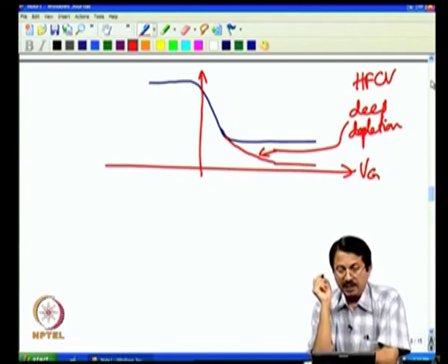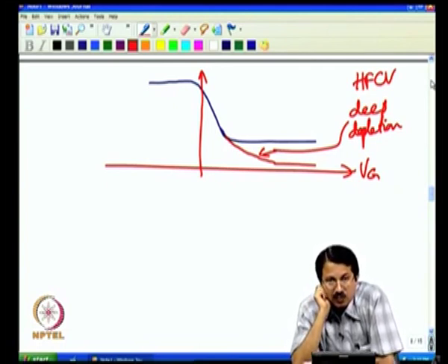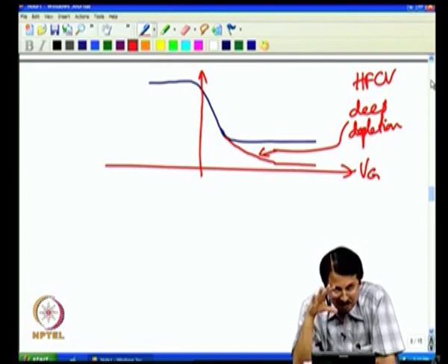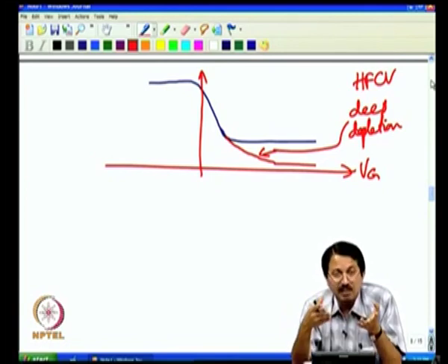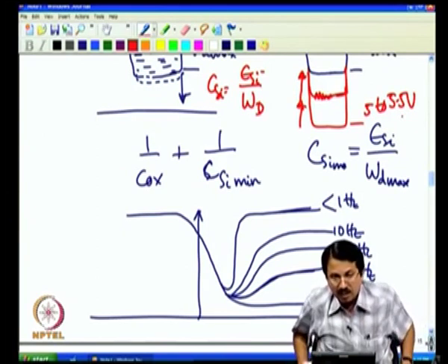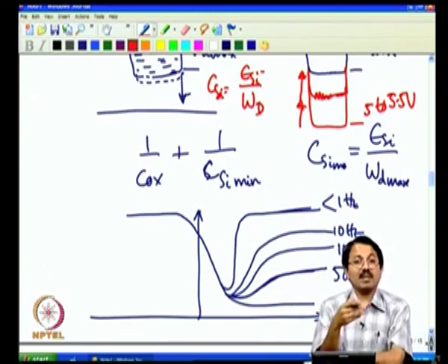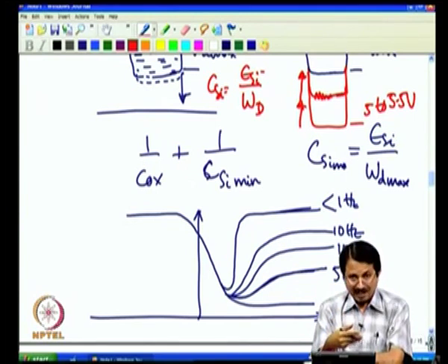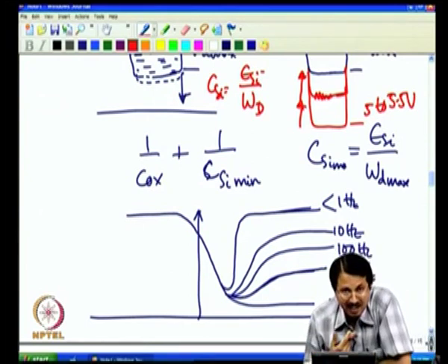Okay. Now, maybe at this time it is also important to mention, when you do CV measurement, you should do it in a properly covered dark probe station, because you do not want any light to come in. Why? Remember the discussion that we were having so far. In inversion especially, you will have huge errors in capacitances in depletion and inversion region if you have an ambient light. Why? Because ambient light can also generate electron and hole pairs. Okay. So, your electron hole pair generation is accelerated by the light.